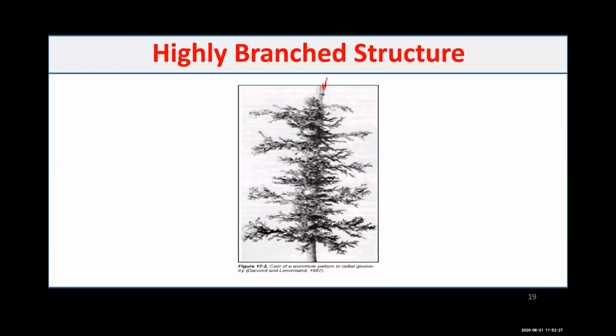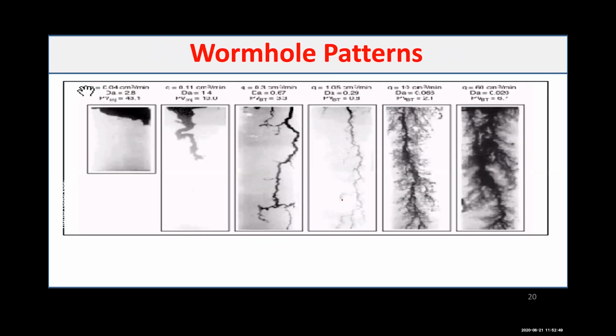So this is your wellbore area. Imagine that's your wellbore. And aside from it, you will have this wormhole, all these high permeability channels that will bypass any damage you can have. One of the main characteristics of the wormhole is the injection rate.